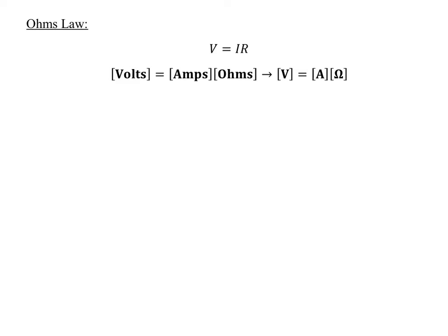across that individual element. So if you know, like an air conditioner, has an internal resistance of a certain amount, and you know the amount of current flowing through the system, you can figure out the amount of voltage used by that actual air conditioner. Now you can also figure out the resistance of an object by knowing the voltage and the current. If you've ever used a multimeter, it has 2 leads. You can attach it anywhere in a circuit to measure the resistance, the current, or the voltage across an element.